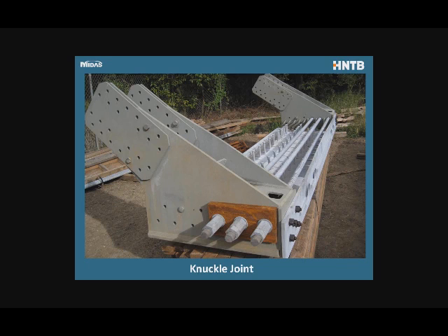But then you have to transmit the thrust that's coming down from the arches and get that over to the tie girder, to the post-tensioning tendons, and that's what that shear stud plate accomplishes. The bars with the nuts are actually there for bearing replacement. When you have bearing replacements, we place jacks just inboard of the arch rib, and that creates a huge moment gradient, and the nuts are needed to develop the rebar more quickly through that knuckle joint.